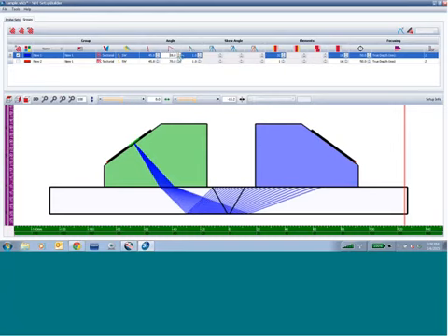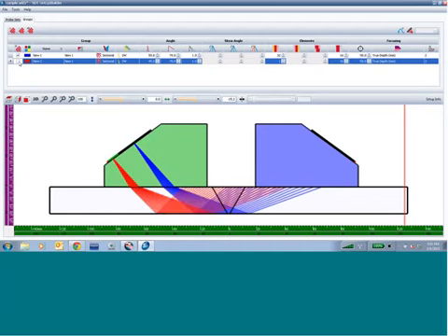I needed the bevel face covered with angles from 50 to 70. So if I adjust my angles, with this blue one by itself, I'm short, but I will add to that a secondary scan at the back to make sure that's overlapped with the right angles.